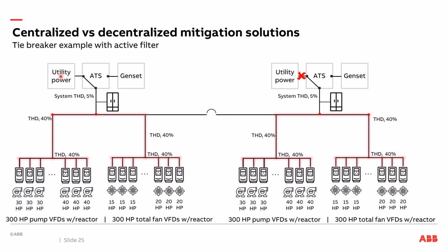Typically these transformers are oversized a little bit, and they're looking at it saying, you know what, I'm not going to be running like this 24 hours a day, 7 days a week, 365 days a year. It's just I'm going to really push this transformer for a short period of time until I can get things up and running over here. Because you're really pushing that transformer in that situation with this tiebreaker closed, which now feeds everything, you need to make sure that transformer can survive and last that. So the last thing you want to have is this transformer now being exposed to additional harmonics.